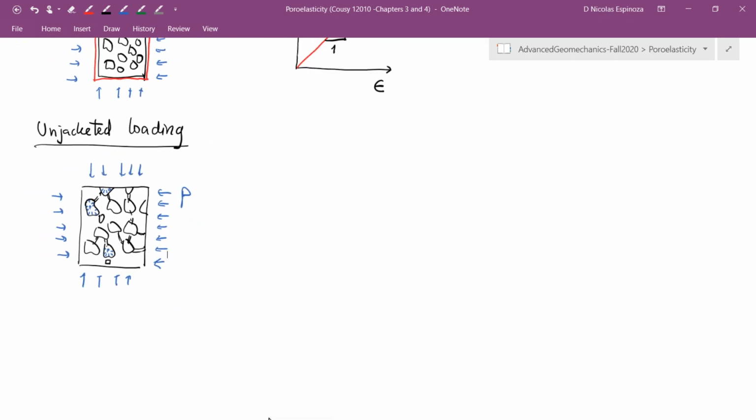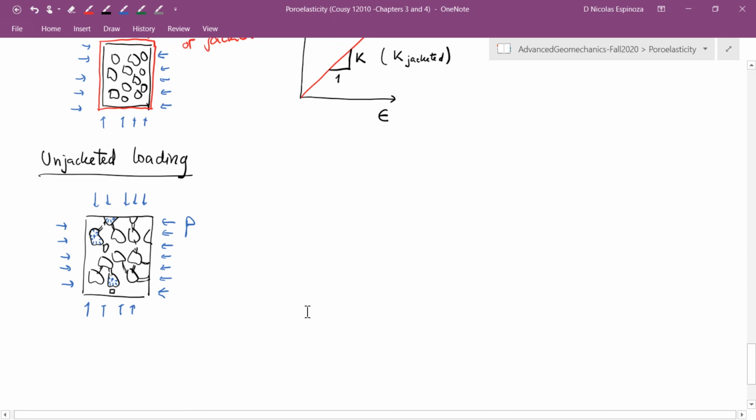schematic. Let's go now to the equations, and let's use equation number 1. All right, equation number 1 tells me that this equality is going to hold based on what we derived before. And now the mean stress that I'm applying is equal exactly to the pressure. That's going to be the total stress. And since in this case the pressure is going to be a compression and we are using the regular mechanics convention, then this is going to have a negative sign and it's going to have to be negative P.